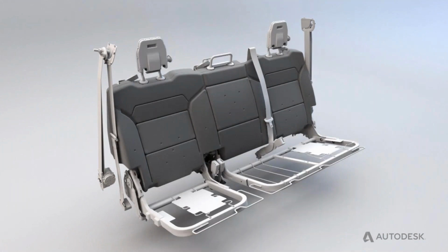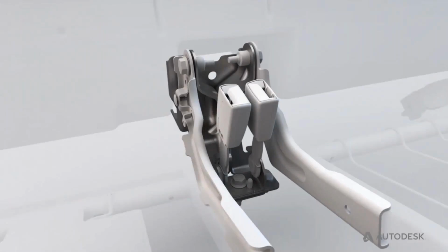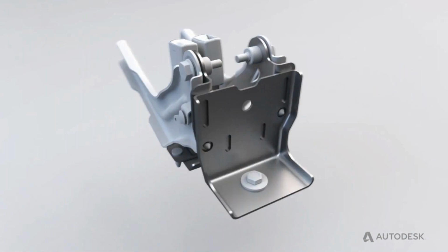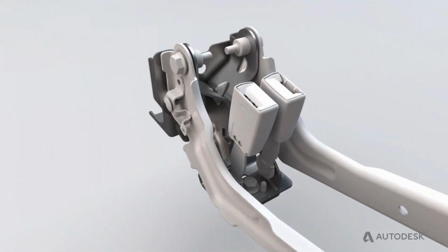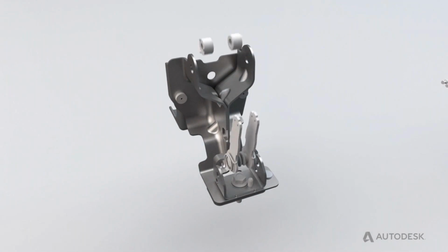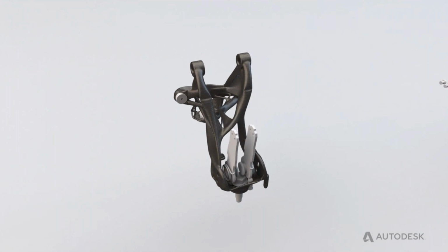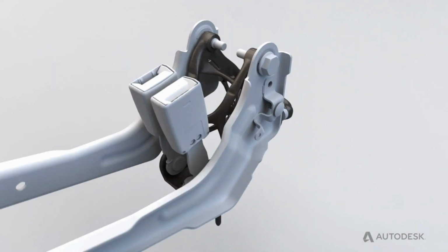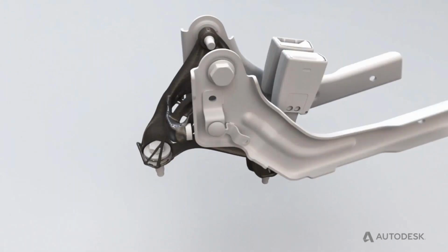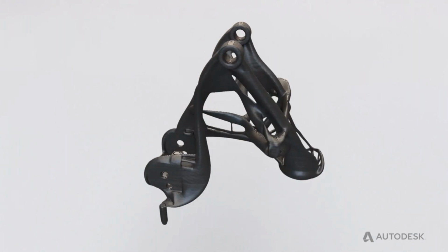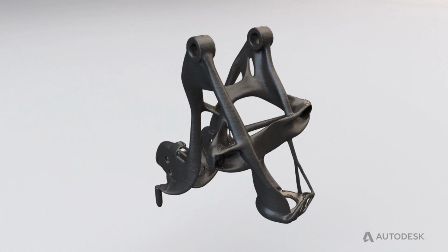So when you're looking at any project you might have, the first thing that we have to do within generative design is take our existing assembly and break it down to what we call the preserved geometries, which are essentially the keep-ins, and then the obstacle geometries, which are the keep-outs. We'll show that on an end-to-end workflow later, but that's really the only geometry consideration that we have to make.